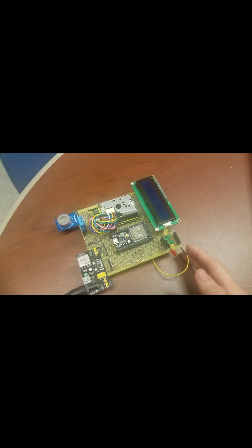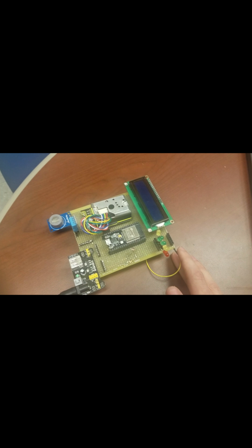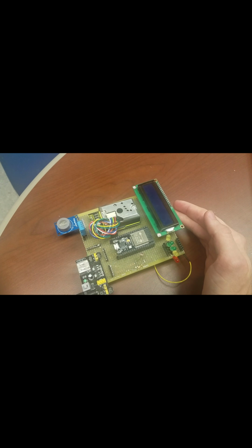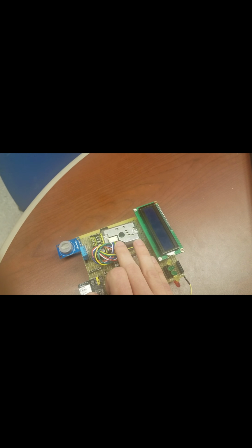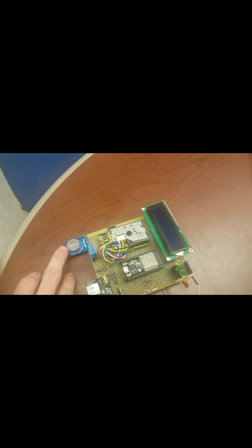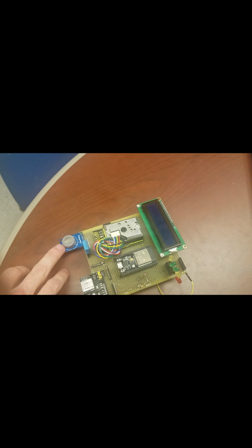And then on the side we have LEDs that will light up in hazardous conditions, an LCD screen that will display the text values of all the sensors on the board. And then we have the particle sensor on the top, which will show the purity of the air. Then we have the MQ7 carbon monoxide sensor over here showing the toxicity. And then we have a DHT11 that will show off the heat and humidity of the system. And then we also have a photoresistor to simulate how much light there is in the room.